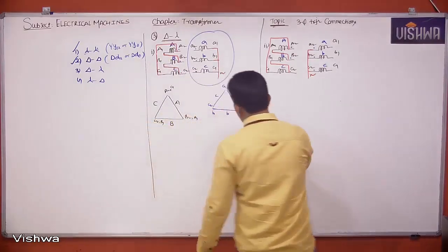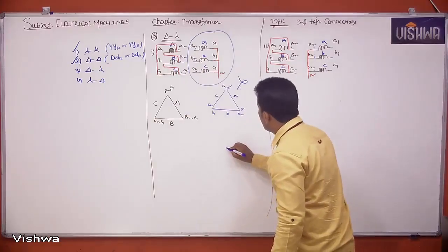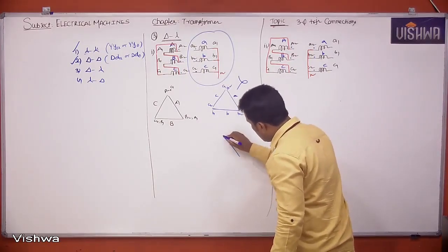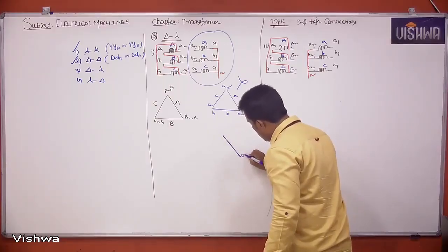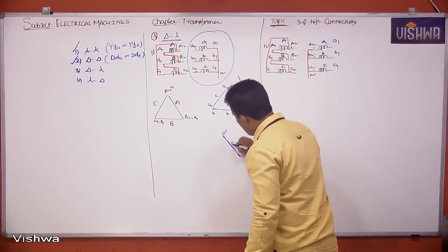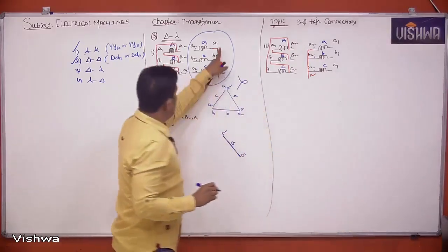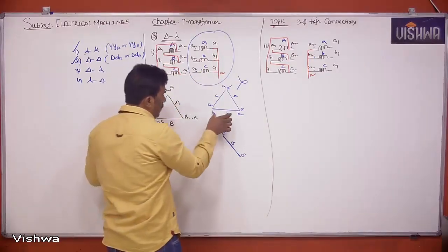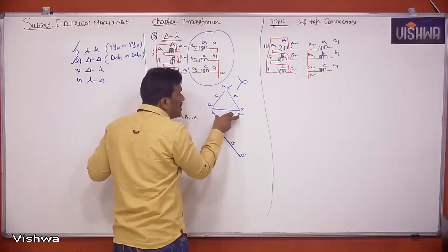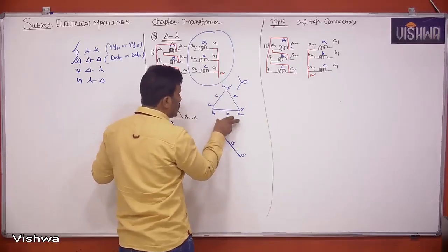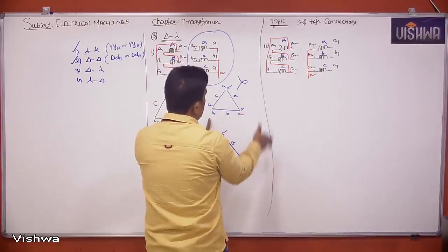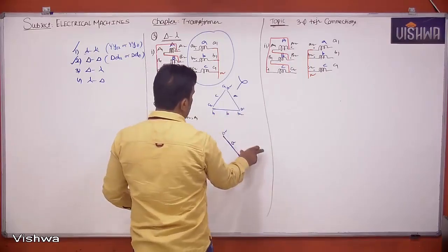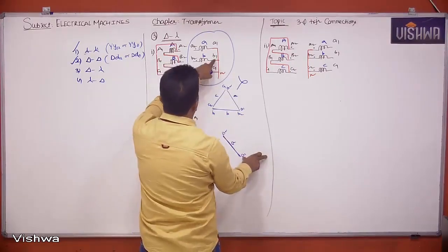From this wrong one, you have to write the correct one. How? You just take any one reference. Let me take the A1, A2 vector, nothing but the small a vector. Here A1 is shorted with B1. That means wherever the B1, B2 vector is, this orientation should not change. B1 should be here, B2 should be here, it should be left side, right side. At the same time, B1 should be shorted with A1.